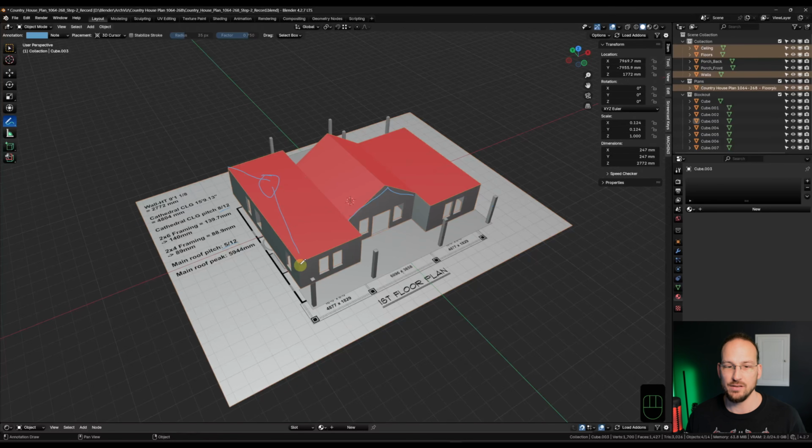I don't have any information on the overhangs here and on this side. And with that, I also don't know exactly where the ridge is going to be. And the type of roof and the framing is also something I do not know. So for the overhangs, we'll have to go with averages. And then from there, we can determine the ridge. And for the framing, I'm just going to go with a 2x4 truss system. It's a residential property. Since I don't have any information, that's what I'm going to go with. I'm not going to go into calculating them if it's 2x4, 2x6, doubled up. That's what engineers get overpaid for.